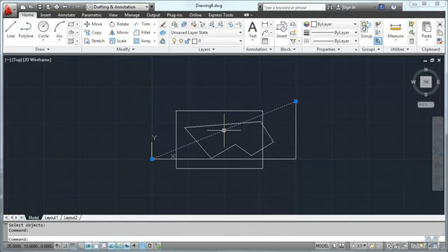You can also do it the other way around. You can click on Objects. Say I don't want that object. Let's hit the Escape button. Let's say we want to just pick off this. So I'm left clicking around. I think I just hit the wrong one. Oops, hit the Escape key. Let's just click around and take that out, and then choose the Erase button, and it deletes them that way too. So you can do it either way. Many of these things are like that. You've got command line options, you've got menu options, you've got select options. There's always more than one way of doing everything.